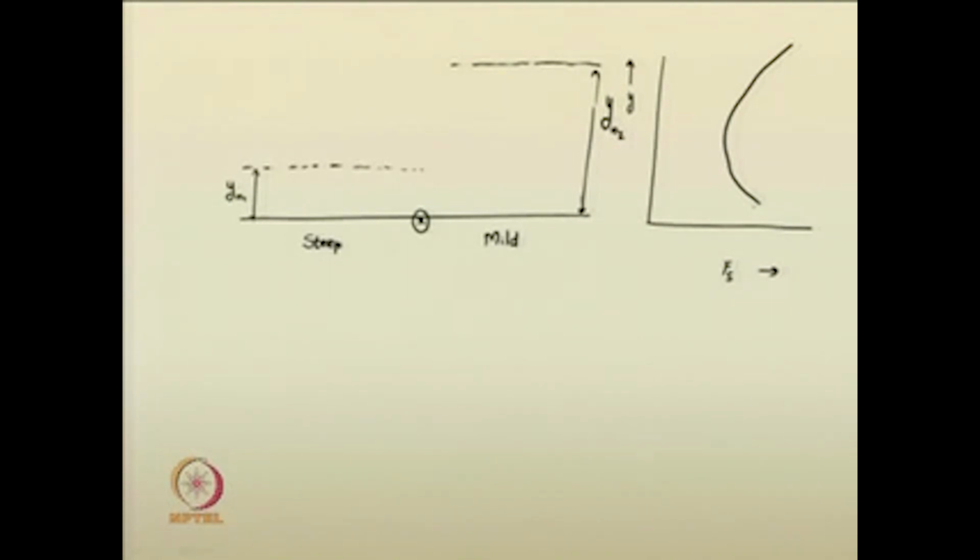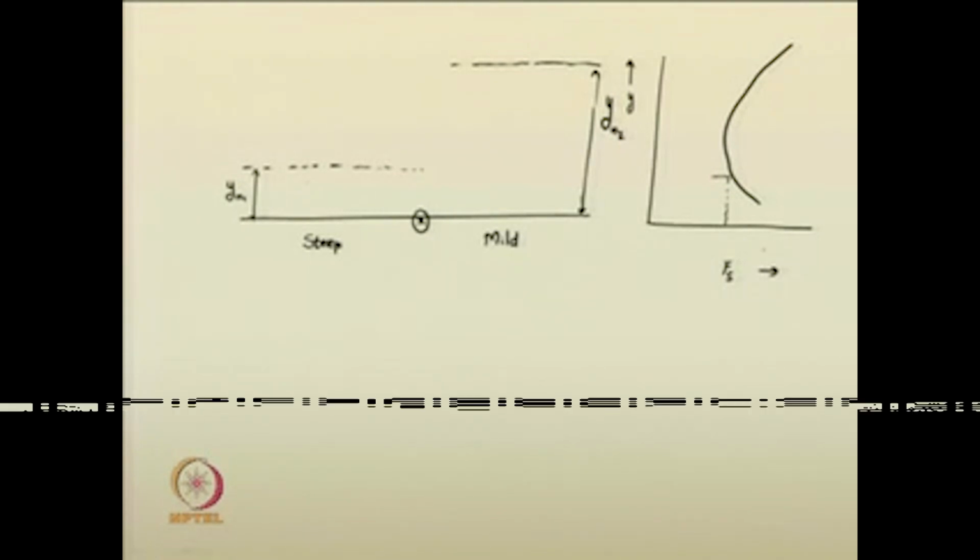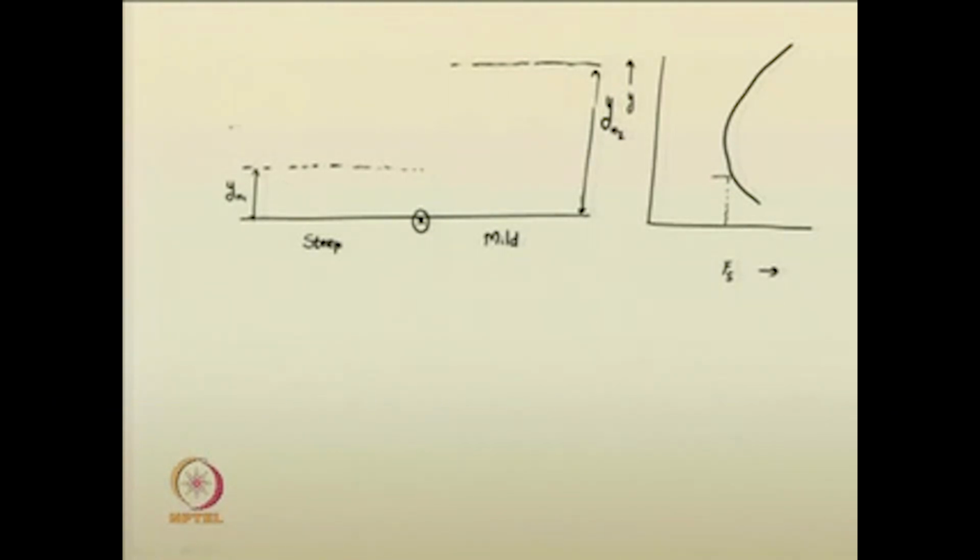Okay. You can just note down the corresponding specific force based on the normal depth in the steep channel, because the flow is occurring from the steep channel to the mild channel.